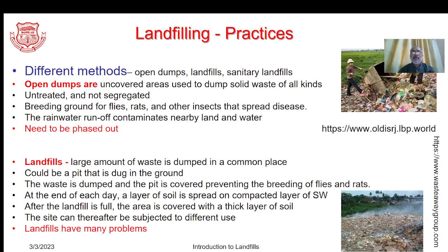As it comes across water currents, the inherent moisture content that waste has will give rise to various gases as well as some unnecessary liquid product, which is leachate, coming out of that, and hence it has the potential to contaminate even the underground water currents. Hence, both these kinds of landfilling practices are very serious and must be phased out as far as the landfilling technique is concerned.